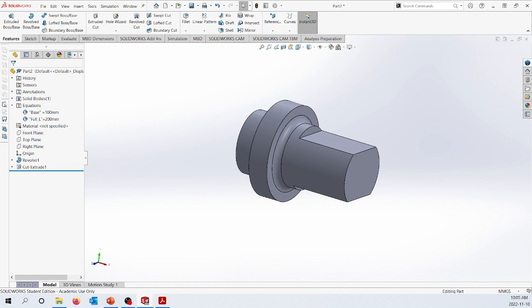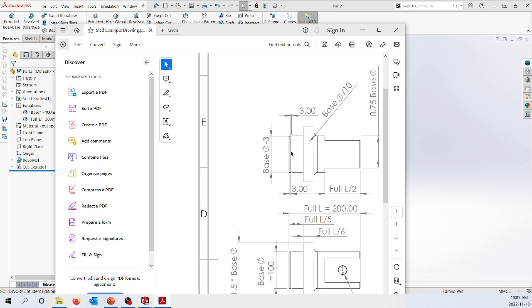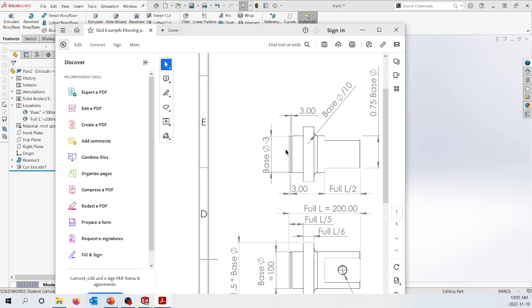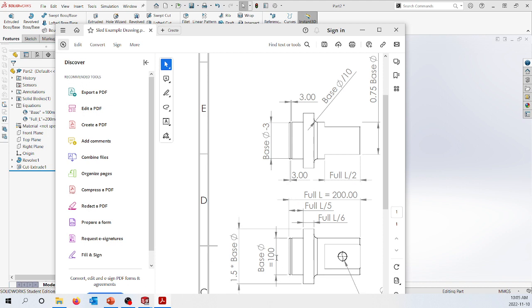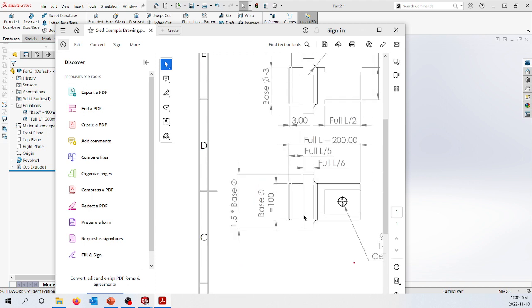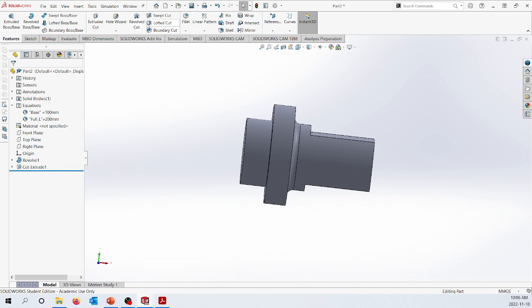So next up, flat faces, tapped holes. Oh, next up, let's add that little groove. So in our drawing, we have that groove for the circlip, right? Just a little tiny one, 3 millimeters, 5 millimeters in from the end. Oh, I really need to fix this drawing. And its depth is very skinny. Its base, oh yeah, it's the base minus 3. So let's put that groove in.